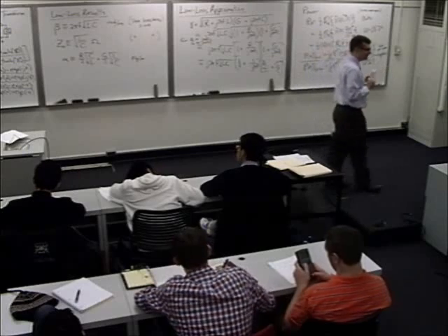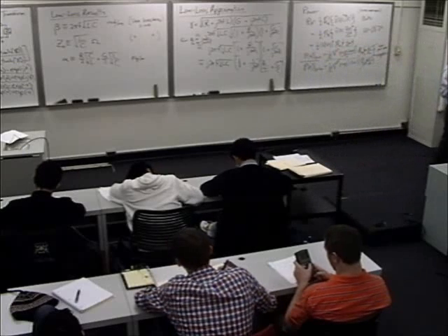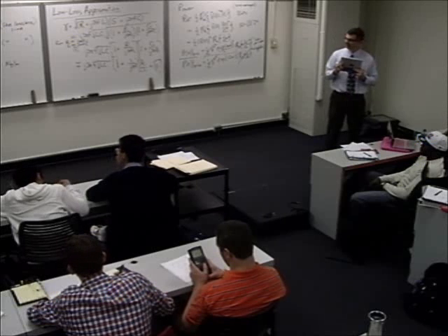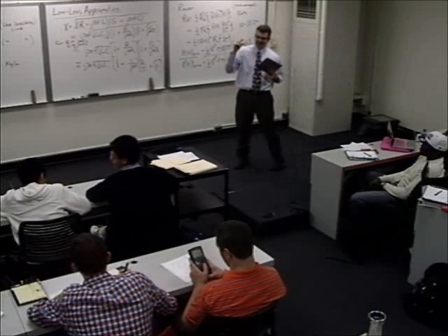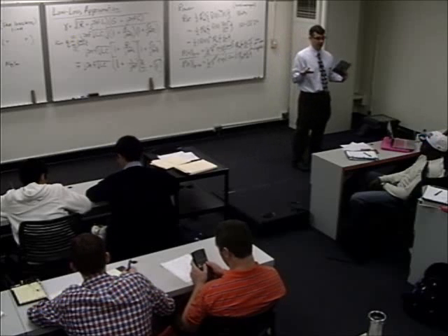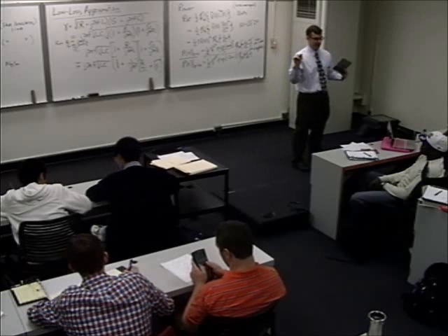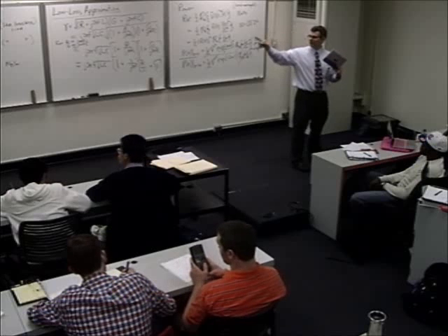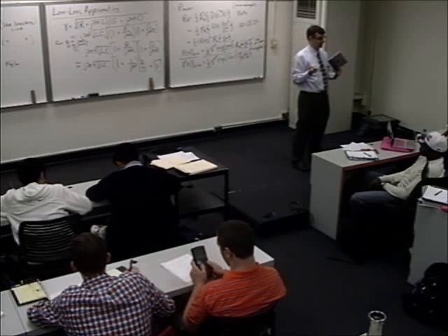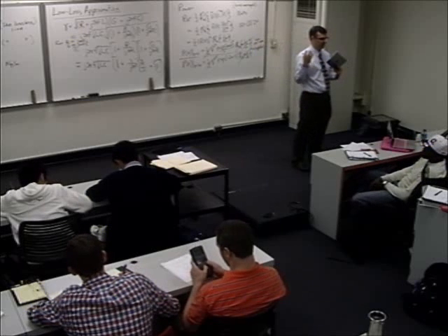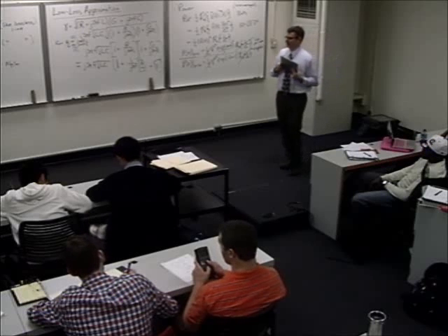Yeah, Cameron. So that's what happened to the normal j. That would be like Z0 j tan of beta d, and the other formula is the hyperbolic tangent. That's right, it brings the j in. When gamma, your propagation constant, was purely imaginary, in other words there was no attenuation coefficient, gamma is equal to j beta. If you plug that in and work through those trigonometric identities, you can show that the formula you learned for the lossless case was really just a special case of the really ugly, full-on hyperbolic tangent formula.